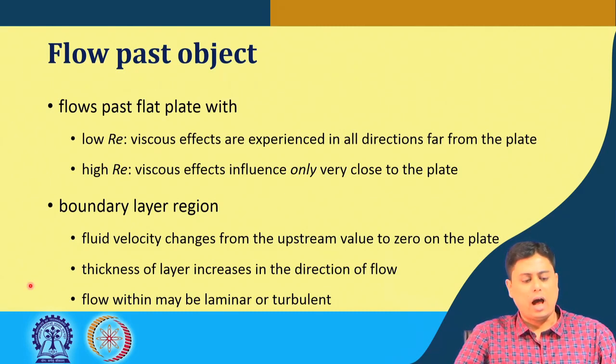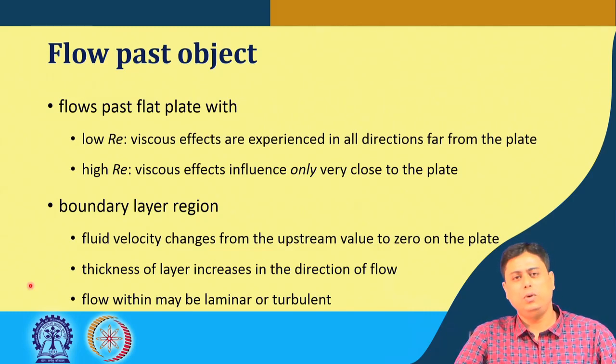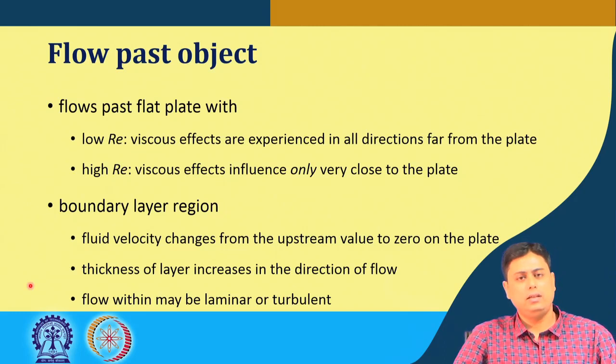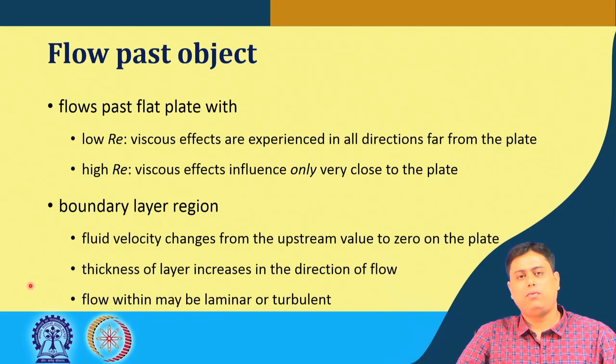So, here high Reynolds number cases mean that there is a huge effect of the inertia, and naturally the viscous effects are less experienced over a broader region. It is mainly contained within a smaller region near the plate. High Reynolds number cases can also be thought of as having very low viscosity. Although for a real fluid there is a substantial amount of viscosity, there is a flow called